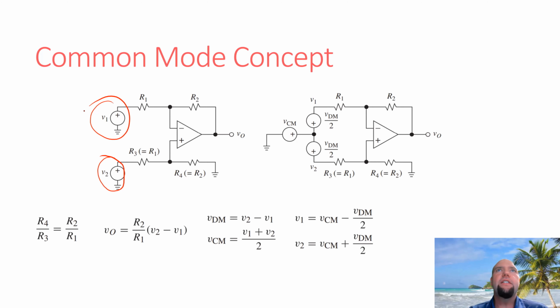As it's coming back to you from this solar cell a kilometer away, I'm not quite sure why this is our experimental setup, but both of these wires have picked up a lot of noise. So they have all this wiggling on these two signals. But the signal you care about is the voltage across those two wires. The signal that's shared between the two signals, we view as what's called the common mode. The common mode is usually not what we're interested in. We're interested in the difference, which is described as the differential mode.